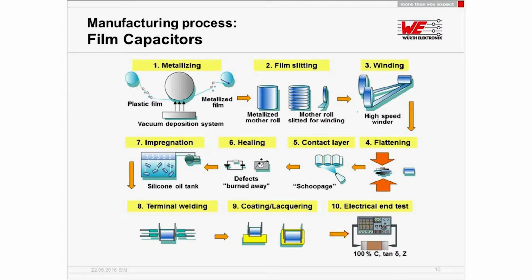The seventh step, you see here, is a step that was often done in the past. It's not so common nowadays. It's an impregnation process that you can do, for example, in a silicone oil tank, where you impregnate the dry coils. Because if there's oil, later there can be no water, because it's every time problematic if water can creep into a capacitor coil, especially in case of film capacitors. If water creeps into such a coil, you get less isolation resistance, so it can easily happen that there will be a shortage and damage to the capacitor.